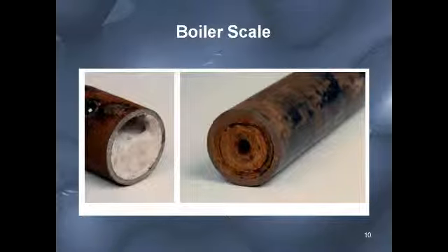Remember too that softened water can cause problems such as the formation of hard silicate scale. Unsoftened feed water contains calcium, which will produce a soft scale and sludge in a properly treated boiler. And this soft sludge carries down the hard scale formers like the silicates that are naturally present in water supplies. Water softeners remove this calcium from the water, and with no soft sludge, the hard scale can form on tubes more easily.